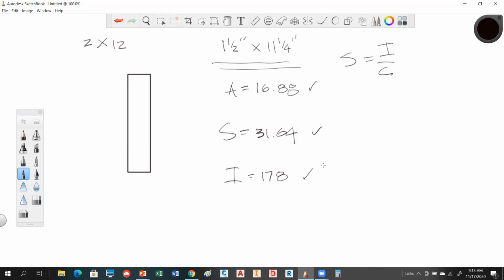But that chart applies to timber, and in chapter 12 there's going to be some problems where you do that. So make sure that if they tell you it's a wood 2 by 12 or whatever it is, that you have to get the dressed size. All right, is everybody okay with that? We're going to work a lot more with this on Thursday, so that's kind of leading up into that. Okay, any questions then before we move on?